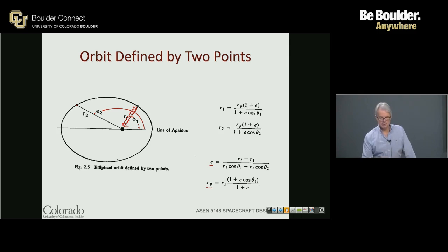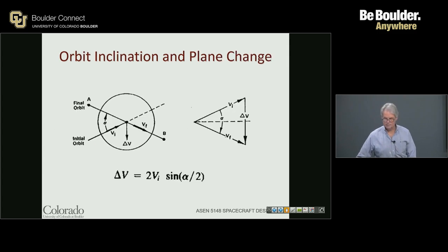And you can imagine that as more and more signals are provided, we become more knowledgeable about the location of the spacecraft, right? So ground antennas become important in terms of solving this. So again, very simple, very straightforward to be able to calculate the orbital eccentricity and the radius of periapsis, and that gives us essentially the definition of the orbit in 2 points.